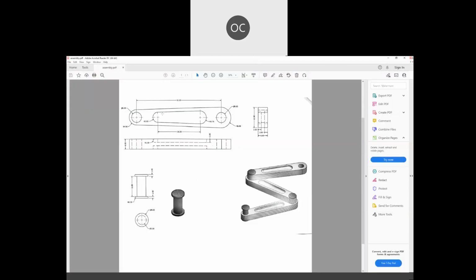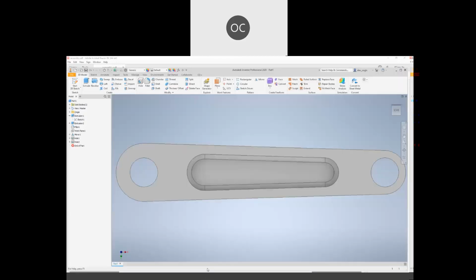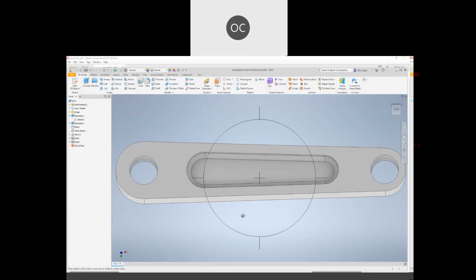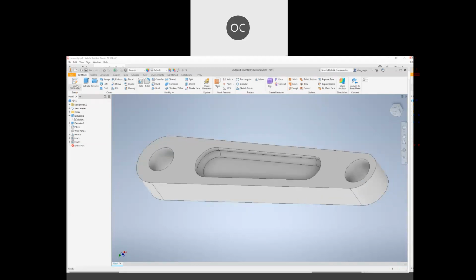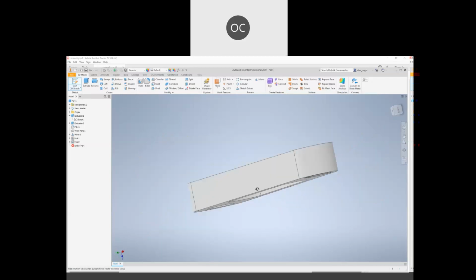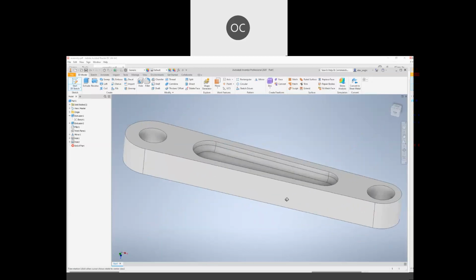Next one, I would like to add on to this. I would like to have a text creation, then I will do the emboss or the engrave features. I will just show to you that. Okay, so I would like you to create 2D sketch again. Okay, please go to 2D sketch. Then click on this surface, please. Okay, the inner surface here. Okay, either side also can, no problem. So 2D sketch, please go to click on surface here.